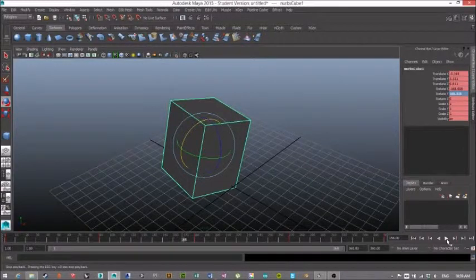You can control that in post-production as well by actually extending out the frames. But say you render an animation and you were to animate this at 180 frames instead of 360. It'll start jumping a little bit more. But also, if you render at 180 frames instead of 360 frames, you have half the amount of rendering, and then you have half the amount of time you're waiting for it. So that is a productive thing and something to consider at the beginning.